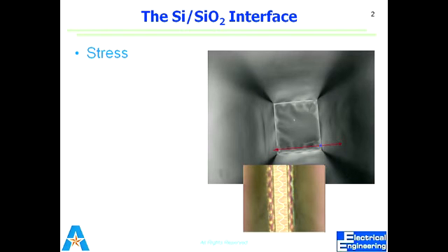So that's why, due to the TCE, that is thermal coefficient of expansion, the change in the thermal coefficient of expansion causes that residual stress. So when you cool down or heat up your wafer, this stress should come into account, because silicon oxide has 5 times higher thermal coefficient of expansion as compared to silicon. So due to that difference, there would be a residual stress.